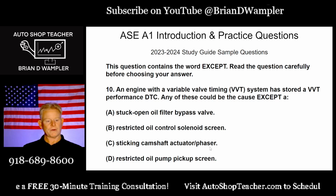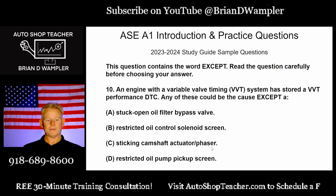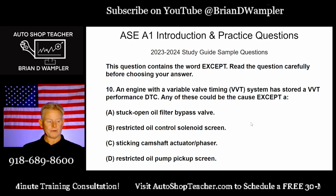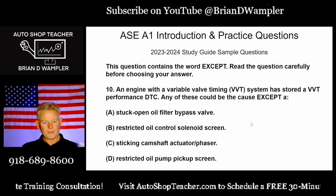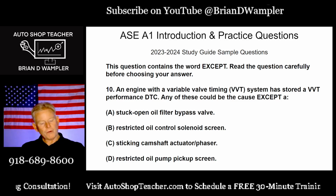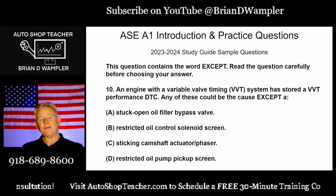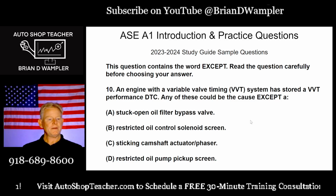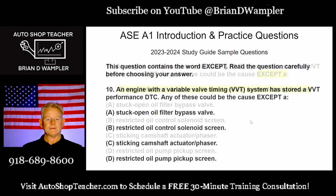Some manufacturers call them actuators, some call them cam phasers. Restricted oil pump pickup screen. Think about this one. So hopefully a couple of these you're already thinking, yeah, that could be causing a VVT fault code. All right, let's look at this.